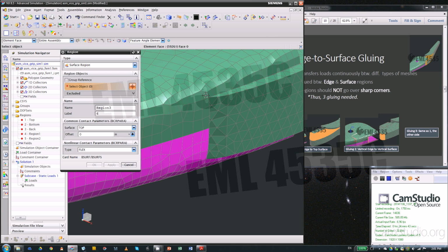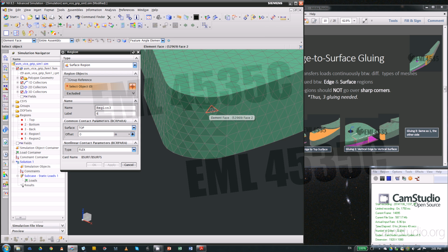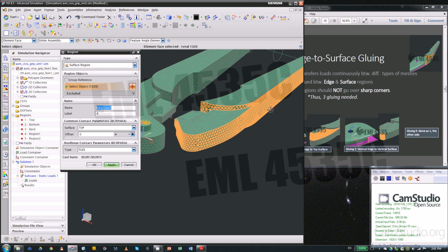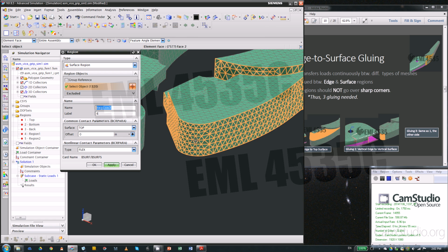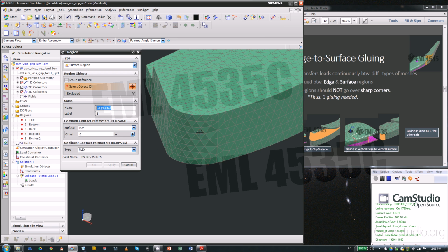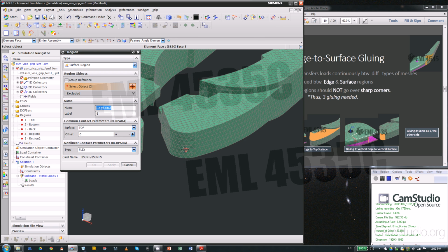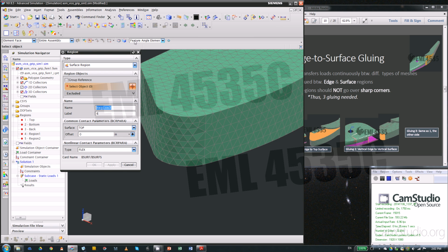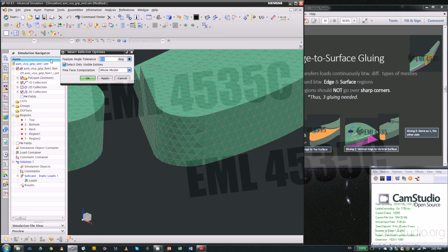So as long as we pick some elements near this region, that's gonna be enough. So let's try pick this. Apparently this feature element edge, the tolerance is too big. So I'm gonna deselect with shift and click. Then change the angle of this feature element edge tool. Let's try 10 degrees. It's probably still too big.